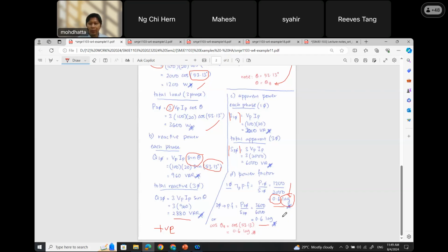components. So here we have power factor calculated using a single phase strategy, and another one calculating using three phase information. The best way to calculate this is by using P divided by S. If you consider a single phase, you must use P single phase divided by S single phase. And if you calculate using a three phase strategy, you must use P three phase divided